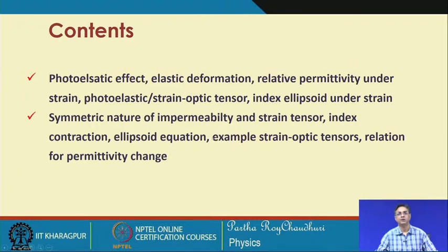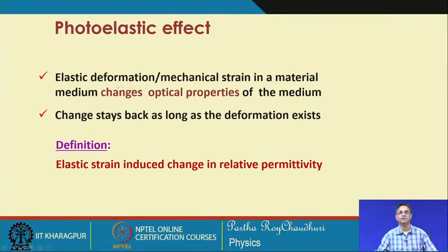So, we will try to bring in how this acoustic wave is changing the refractive index properties periodically along the direction of propagation of the acoustic wave. Elastic deformation, that is the mechanical strain in the medium, changes the optical properties. This is because it creates a periodic compression, periodic deformation in the medium along the length of the propagation of the acoustic wave.